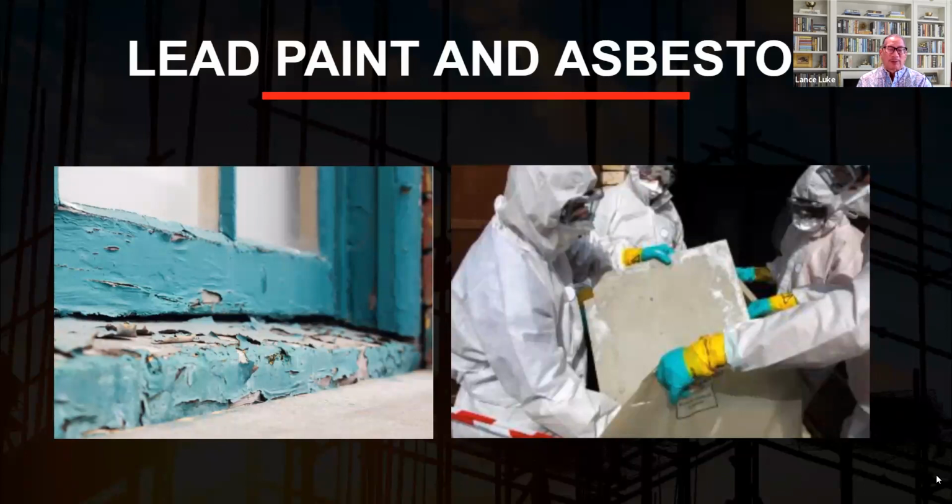And then, recently, that's why the realtors know, and it's in the contract documents, that any house built prior to 1977-78 may contain lead paint and asbestos. Asbestos could be used in roofing, drywall, joint compound, pipe lagging, which is insulation around piping, flooring, these 9x9 floor tiles,